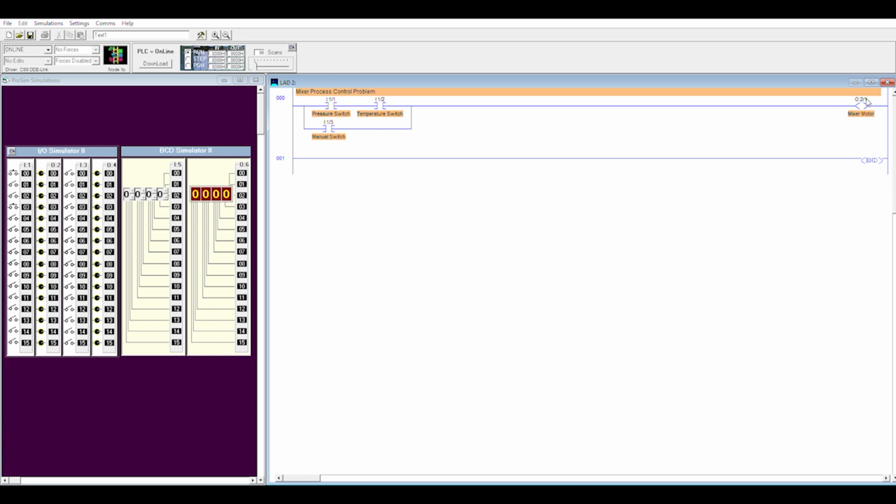The answer would still be a false. Let's go ahead and test that by closing the switch. I'm going to left click on this switch. Remember, it's maintained, so I can left click and leave it alone. We'll notice that the 01, which is the equivalent of an LED on the input card, is lit, i.e. a true. There is power coming in to my PLC from this input device.